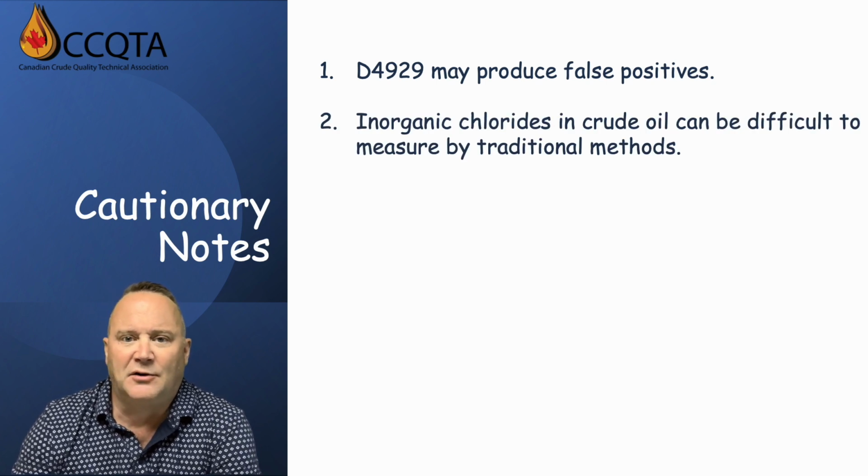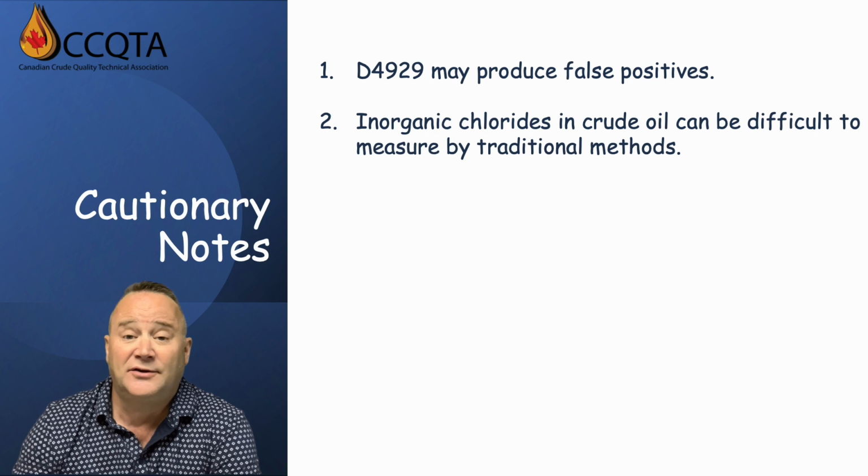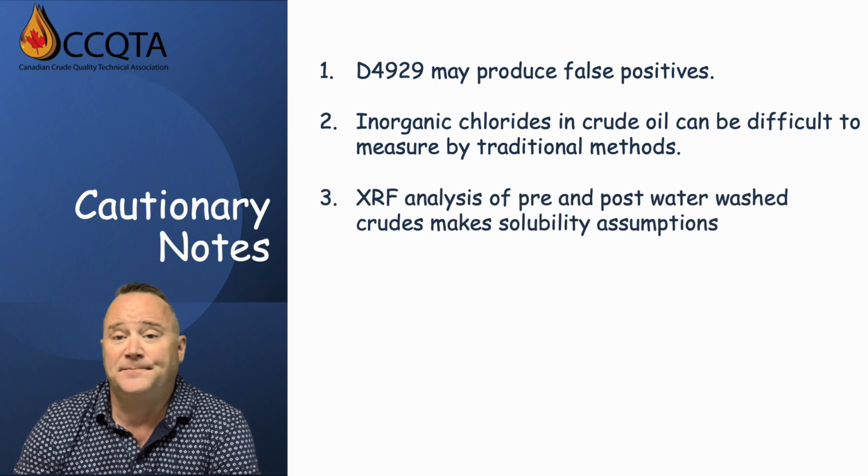Next, inorganic chlorides in crude oil can be very difficult to measure by traditional methods and do require the salts to be soluble in water. Like we've talked about, asphaltene-coated salt crystals like Smarties are resistant to water extraction, so they're likely not going to be detected.